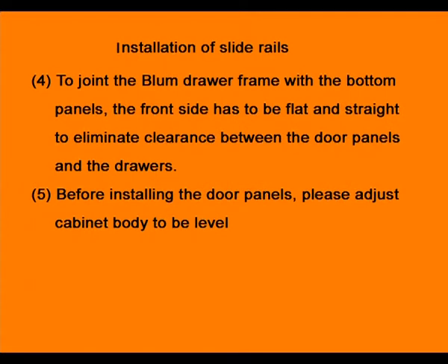4. To join the bloom drawer frame with the bottom panels, the front side has to be flat and straight to eliminate clearance between the door panels and the drawers. 5. Before installing the door panels, please adjust the cabinet body to be level.